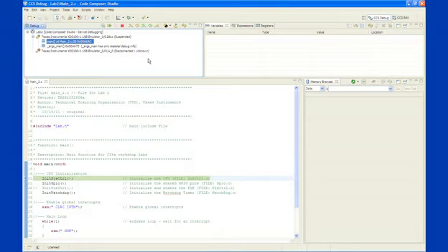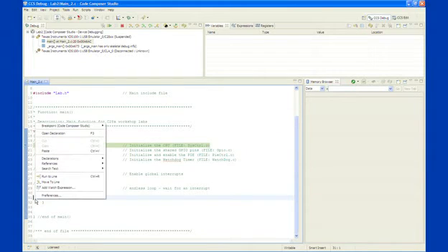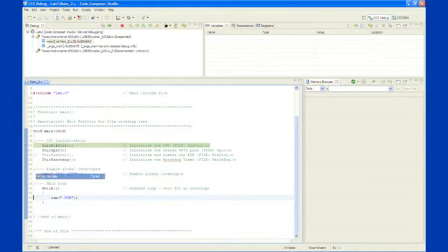If the device is power cycled between lab exercises or within a lab exercise, be sure to configure the boot mode. In this example, we're using EMU_boot_SARAM. Okay, now in main, we want to test out this watchdog. We know it's disabled, and we will go into the loop at the bottom here and right click and run to line, which is equivalent to setting a breakpoint, running to the breakpoint, and removing the breakpoint.